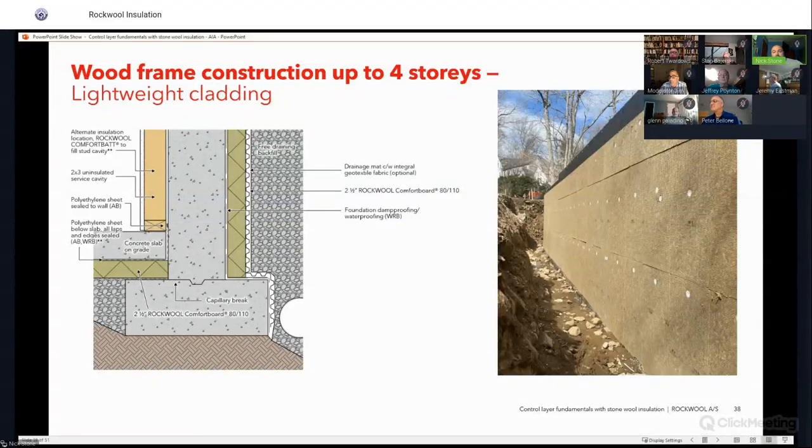When it comes to expansion and contraction, we expand 1/10 of an inch over 33 feet. To give you a comparison, your polyisocyanurate is going to move up to 2.4 inches over that same 33 feet. So even though we just stack these, we don't have to tape our seams, because as long as we have continuity of connections, it's not going to expand and contract over time, creating voids and creating some problems behind that.